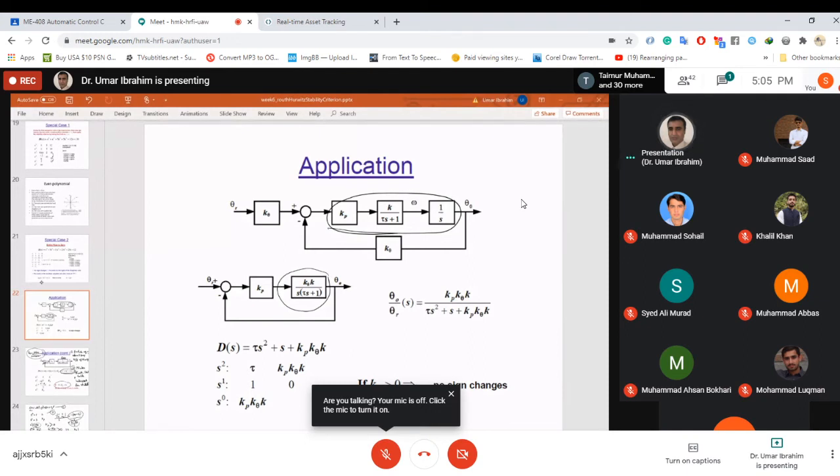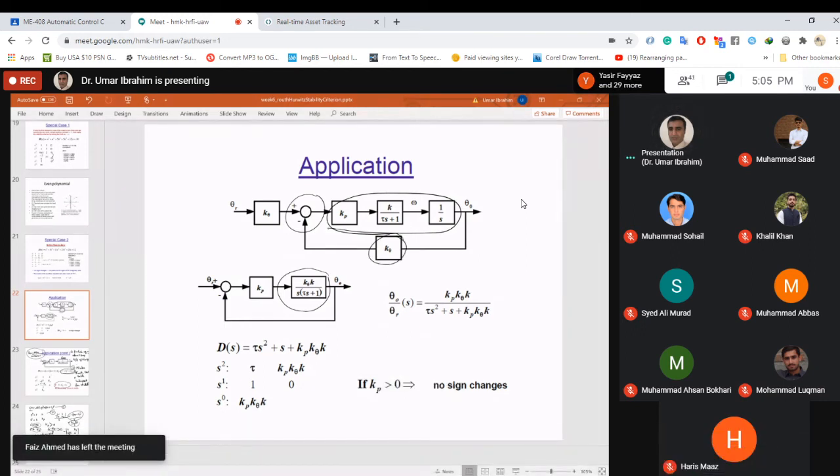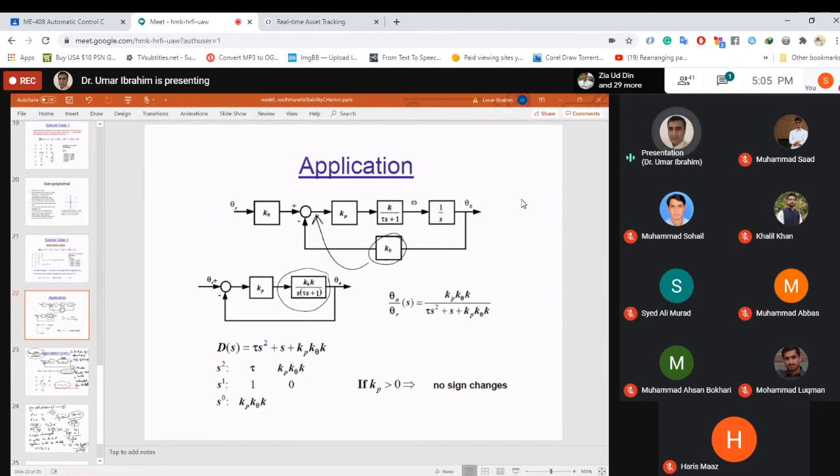from one of the, this is a summation junction. So if you move K theta from one of the input to the summation junction to the output of the summation junction, यहाँ पे ले आए, then you will place an inverse 1 over K theta on all the other inputs to the summation junction. This inverse will cancel out this, and we will end up with K theta up here. ठीक है, ये ब्लॉक डायग्राम रिडक्शन है, चैप्टर 5.